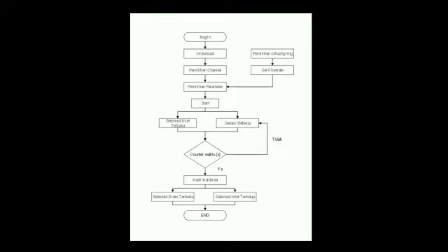The solenoid inlet will automatically open and water will flow from the line to the chamber, which has an infrared photodiode sensor. The sensor will read when there is running water and start the counter. After the first measurement time counter is reached, the results will be processed by the microcontroller on Arduino and displayed in the form of flow rate and volume.